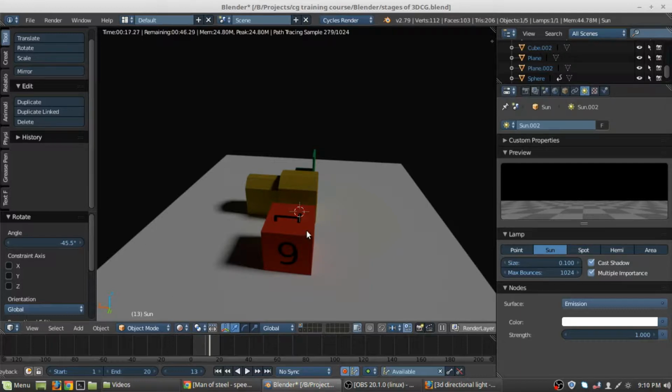Skylight doesn't create any shadow. They come from all the different directions. Now, how do we do that? As I told you before, changing this size attribute or factor will affect how your shadows look. So we kind of know if we crank it down, the shadows will get tighter and tighter, as you can see. If you dial it all the way down to 2 or 3, the shadows are really tight. And heck, if we say 0, the shadows are abnormally tight.